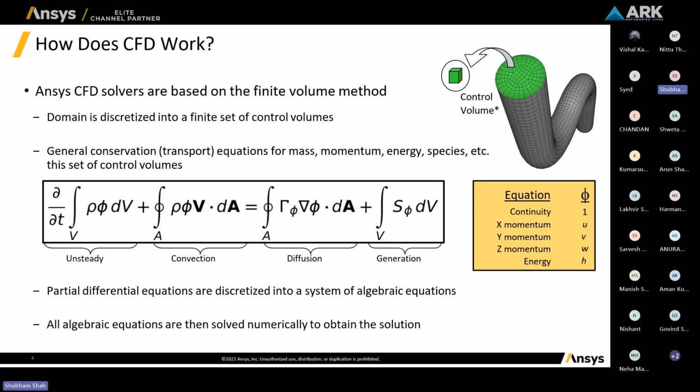Then comes the solver part, where we give our inputs. Let's say we give our boundary conditions. We tell the software that this much inlet of air is going to enter our system, or this much temperature will be there at the initial point when the simulation starts. These are the initial conditions. So these are all known as the boundary conditions, and this comes under the solver part.